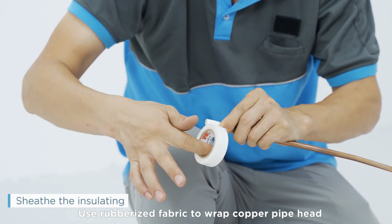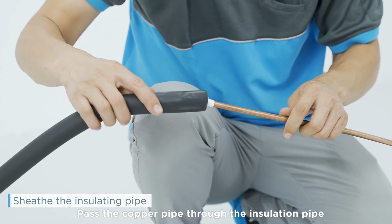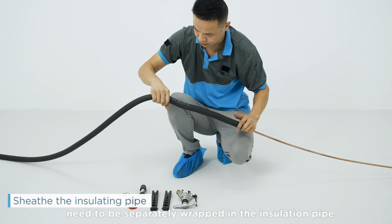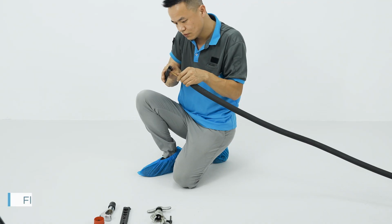Use rubberized fabric to wrap copper pipe head to prevent foreign materials from entering. Pass the copper pipe through the insulation pipe, and the liquid pipe and gas pipe need to be separately wrapped in the insulation pipe and cannot be wrapped in the same insulation pipe. Sleeve the nut. Flaring work.